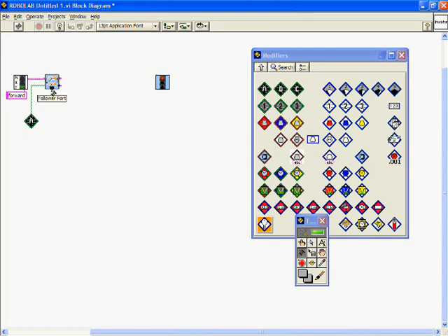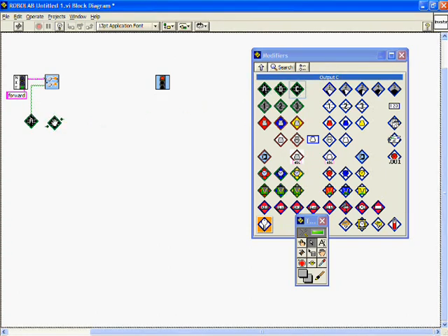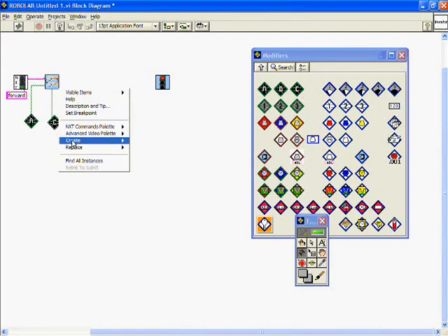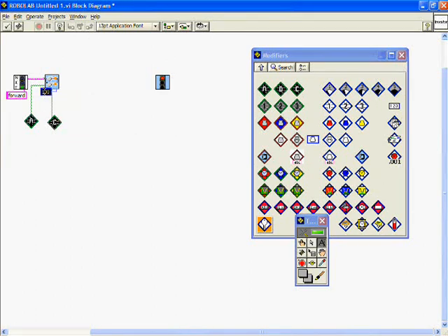The next port we'll look at is the follower port. This is where we decide which is our follower motor. Our follower motor will be motor C, so connect Output C to this port. The next port we'll look at is the speed ratio. This decides what is the ratio of the speed between the two motors. Since we want this robot to go in a straight line, we want both motors to be at the same speed. So we right click over that port, go to Create Constant. 100% means that both motors will have the same speed.